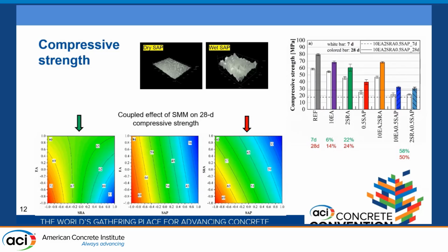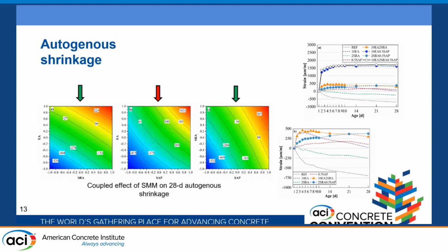And as you compare, you can see at the top, dry SAP and wet SAP. You can see the high expansion of the particles due to the water absorption, and after release of water, they leave voids in the concrete and reduce the mechanical properties.